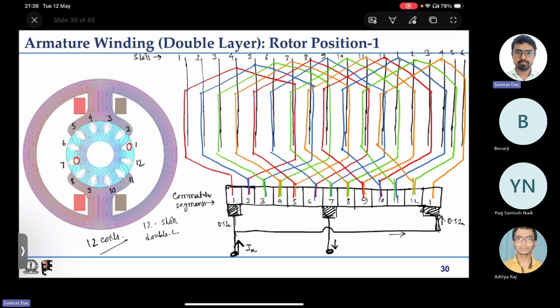because you will find that these will form two parallel paths. So that is what you mean by parallel path in a DC machine, because we are using lap winding. We see that parallel path is equal to the number of poles we have, and we are winding it for two poles, so we have two parallel paths, and this total current will again have to be Ia, and total Ia will be coming out from here only, because both the coils are connected, shown here in the same place, so there is no problem of showing the two brushes in two locations like the other brush.